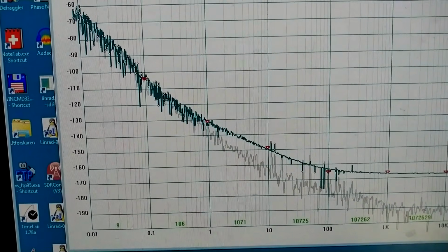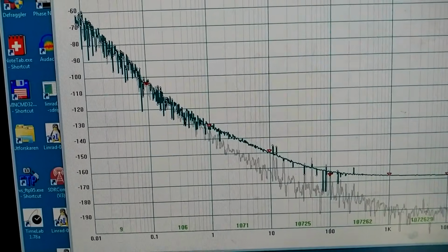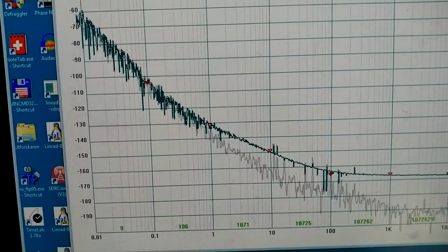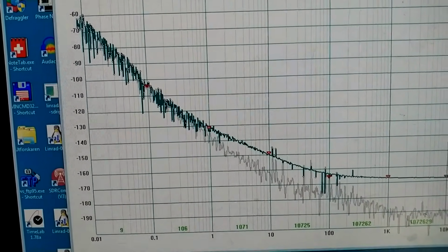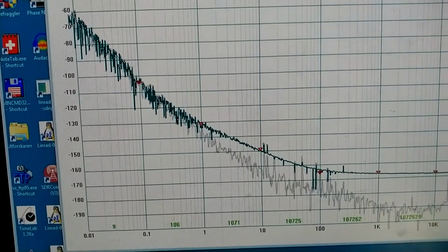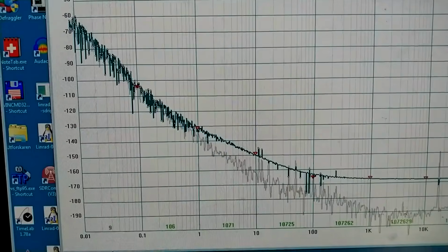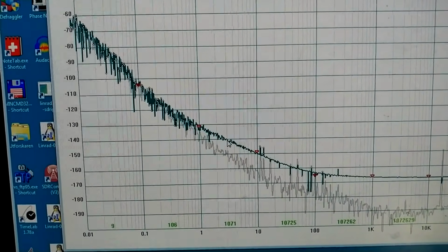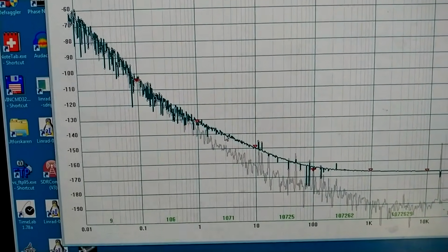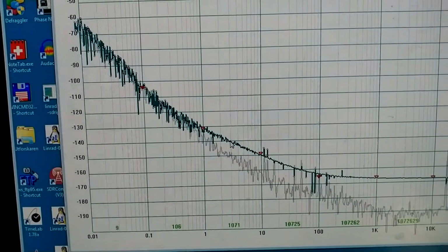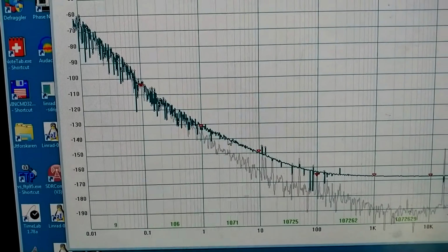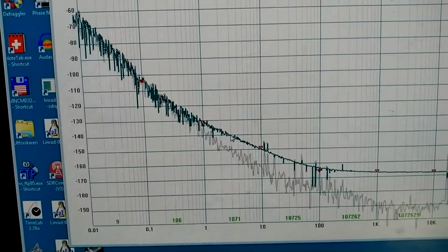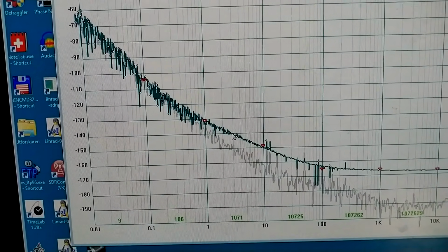I am feeding the source follower through 3 kilo ohms and with the step-up transformer for 12 kilo ohms impedance on the gate. The effect of removing the gate-to-drain capacitance will be much larger when the source is the crystal filter, because small capacitance variations will have a much larger effect when they are parallel with the crystal.